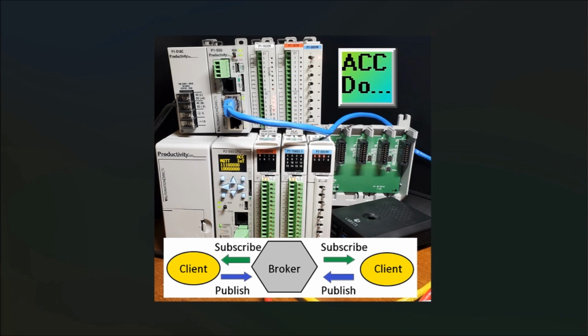It has a report by exception protocol. Information can be published when changes occur. This means less traffic on your communication network. It is a stateful protocol. You always know when you are connected, or who is connected and the way they're connected. You will know if the information is valid or not. So you know when they're not connected as well.